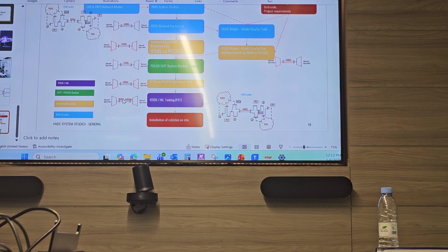So you have to tune this to behave like this one. With small changes of frequency, you will follow around 60 Hz, because it always goes around 60 Hz, ups and downs. Load increases, generator increases, and they're chasing each other around 60.